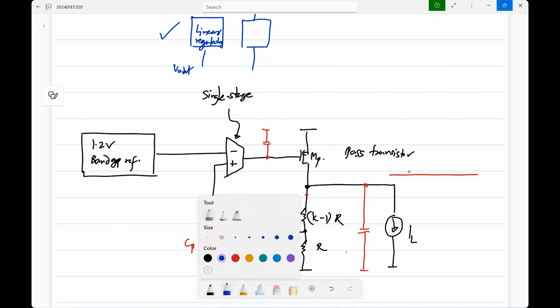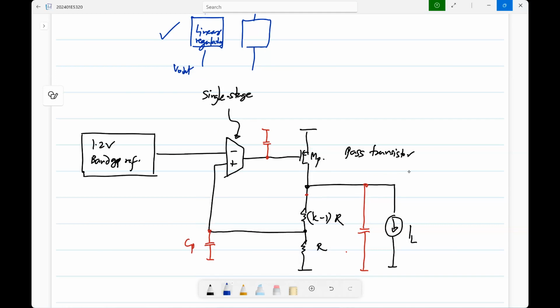In reality, it will have some wiggles on it, depending on various disturbances in this power supply and so on. So one way to minimize that is to use a large capacitor. Okay. So now all these together can bring in some special challenges for stability. Okay. So how would you stabilize this actually? That is this negative feedback loop.